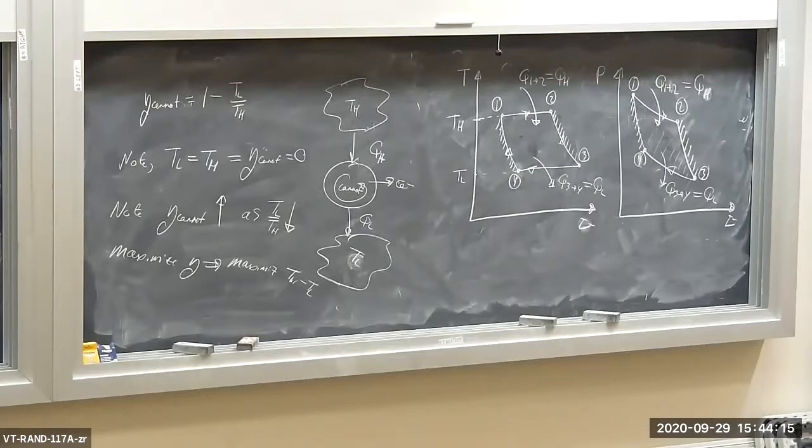The heat transfer to the low temperature reservoir during the cycle is 3.4 kilojoules. The high and low temperature reservoir temperatures are 300 and 250 degrees Kelvin. This is going to be a constant specific heat problem. I'm going to find a quantity called k, which is the ratio of the specific heat at constant pressure, Cp, divided by the specific heat at constant volume, Cv, and I'm going to set that equal to 1.4.